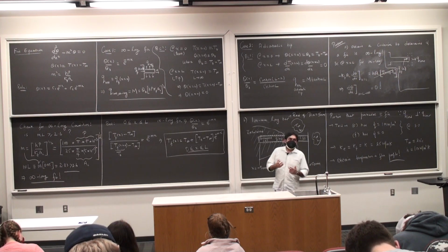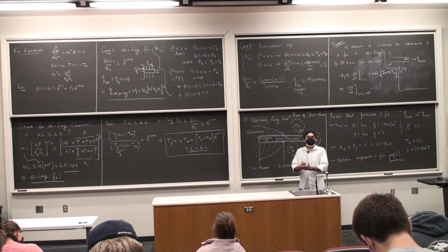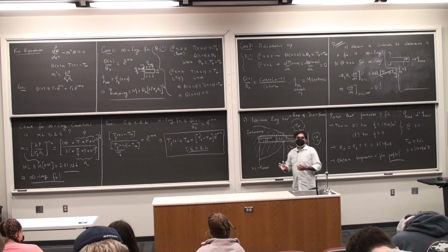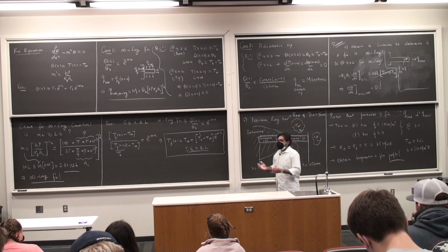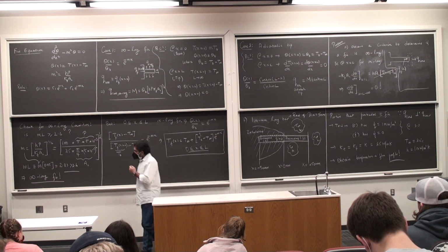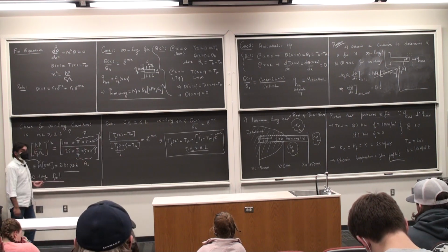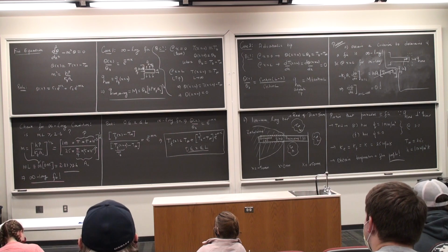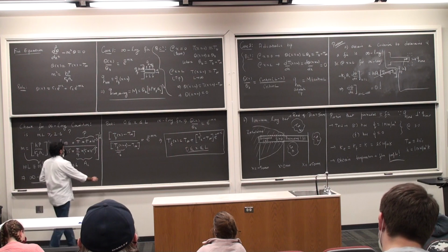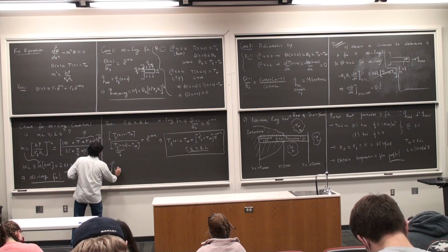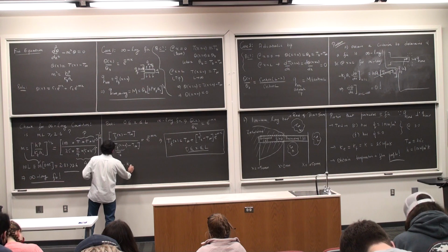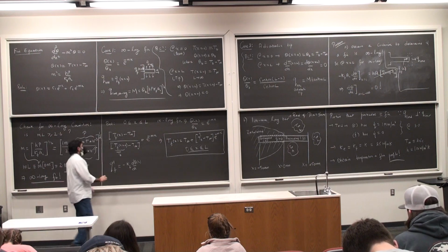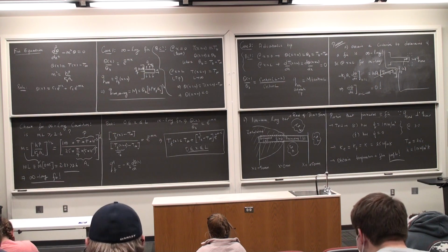In this particular equation, the only unknown quantity that I have is this base temperature T suffix b. So I do not know this guy. We know everything else. T infinity is given to us, 20 degrees Celsius. M, we just calculated that fellow. So one of our aims is to calculate T suffix b using the information given. But hold on to your thoughts. Take the differentiation of that. Write the heat flux as well. So Q double prime fin is minus K fin d theta by dx, which is the same as dT by dx.